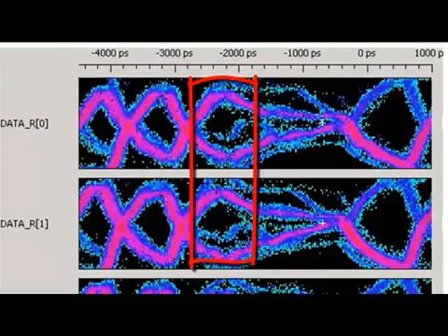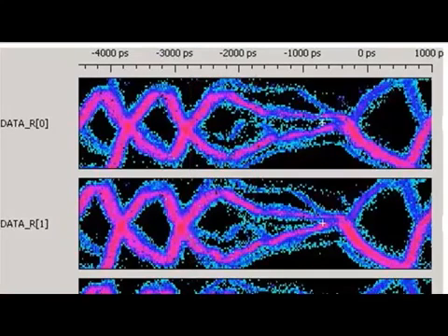In this situation, the bus was being released too soon and was corrupting the last sample of the burst. This unique view was possible with the Agilent burst scan mode.